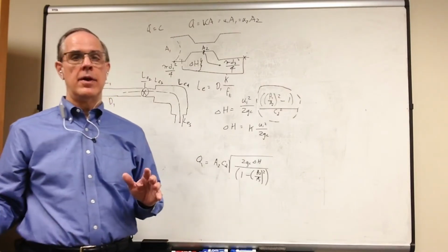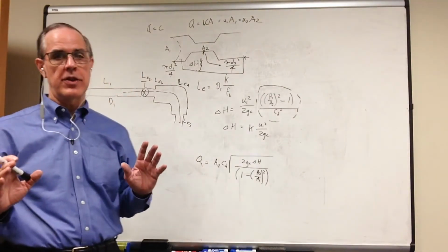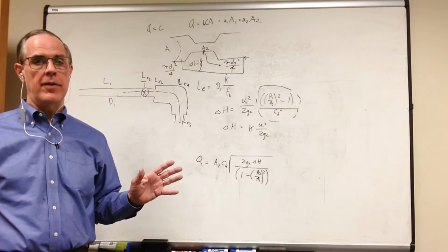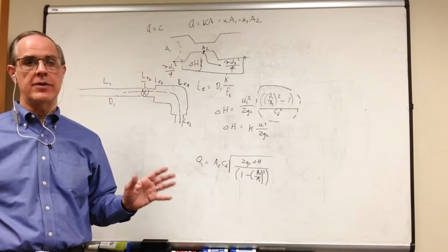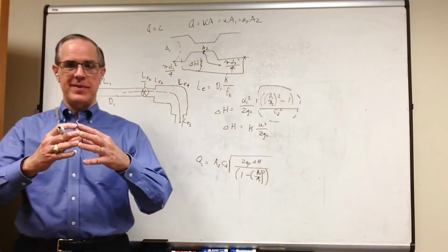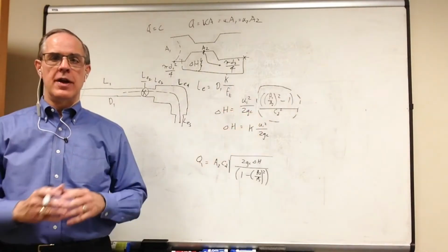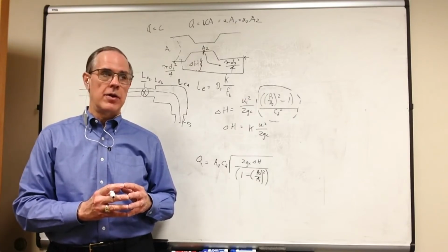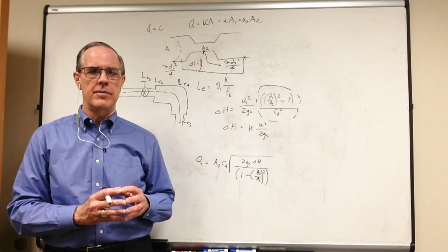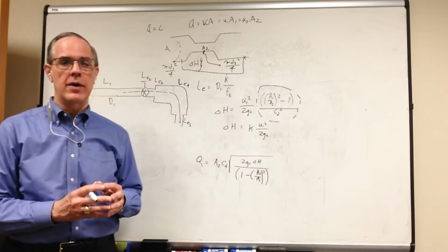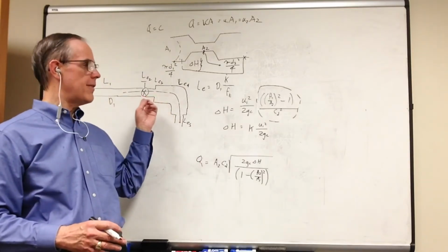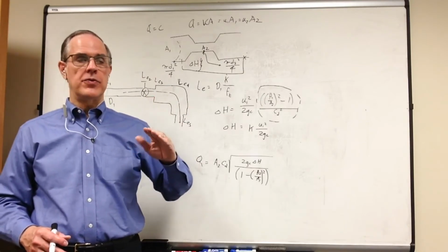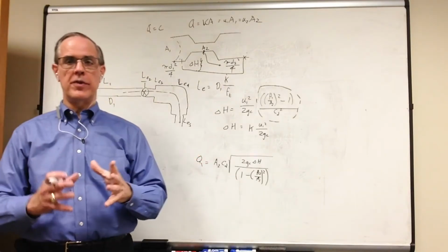And I have in my handout that, obviously, you have to know the roughness or be able to estimate the roughness of the pipes before you give an equivalent length to it. But this is a handy way of taking into account series losses in a fluid system. And I've used it in my practice, and I know other engineers have used it. You don't see it very often, like you should, but one of the things that I do require is for the students to compute the equivalent length of the gate valve, which we use, equivalent to the pipe that's feeding it.